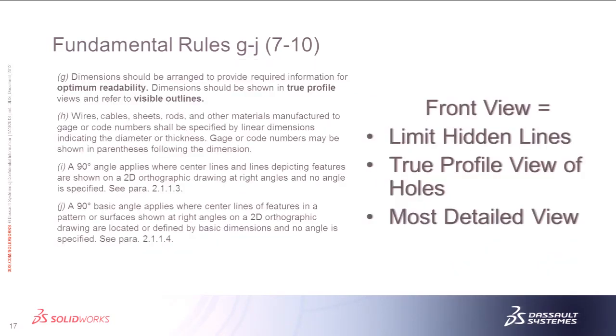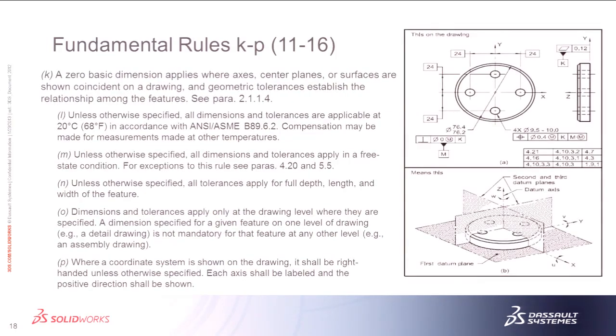So the front view, you want a limited amount of hidden lines. You want to make it the true profile view of your part. It should also be the most detailed view. And then think about looking straight through the holes. That will help you set up your front view. And sometimes those things are going to contradict themselves. So, those aren't shalls, but it can be a bit of a chore sometimes to settle on what the best front view is. That's why we like to go through and get all the views set up, section views, everything before we start dimensioning. Make sure that we think we can get the entire part defined.